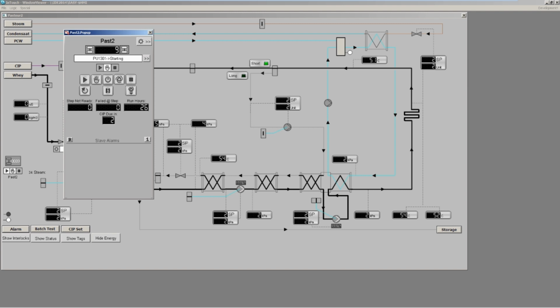The S88 guideline states that a sequencer must be able to be paused, and the operator must be able to go in a semi-automatic way to step through the sequence. We're currently paused in step 11. When this step is started, we will see a start delay. This could be the dosing of a chemical, followed by a siren. The operator is informed what's going on and will never have to question what's happening. Then the operator will be notified that the pump is starting by showing the starting string.